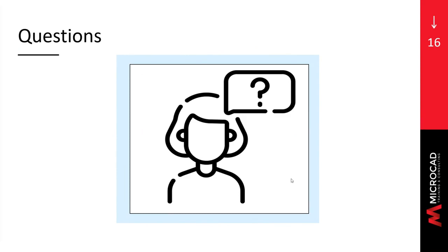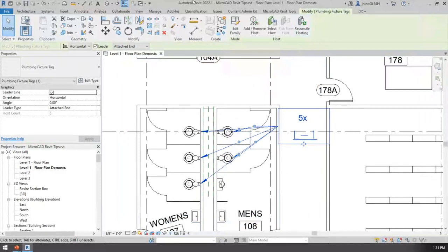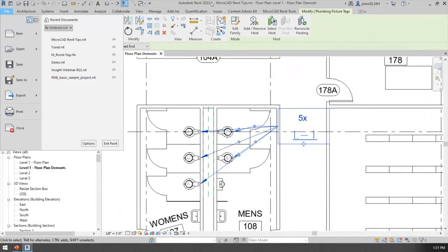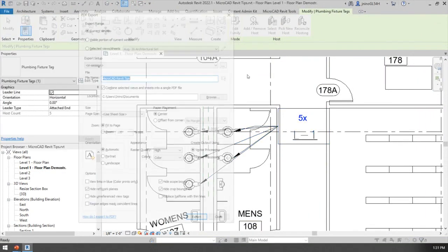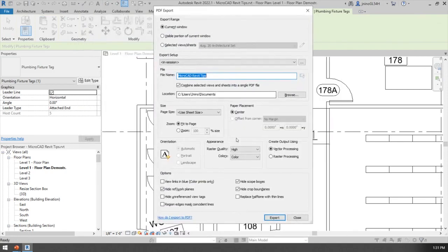Alrighty, so the difference with the new PDF creator, let me show it on Revit. Basically, before 2022, when you came to export and went to create PDF files, you would have a different notification bar with the options to select. With this one, I would say it is a more stable PDF creator that is going to allow you to customize your sets.